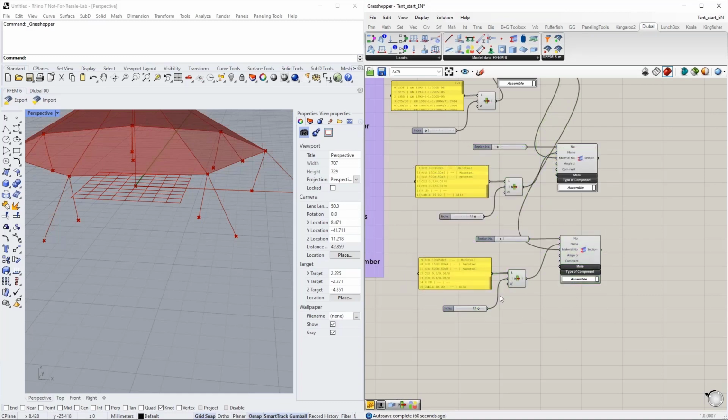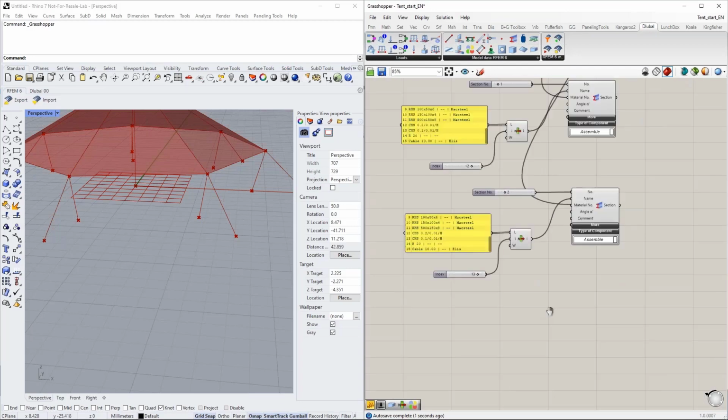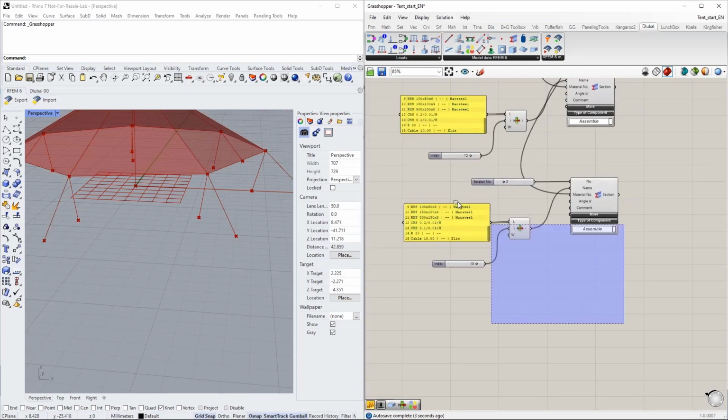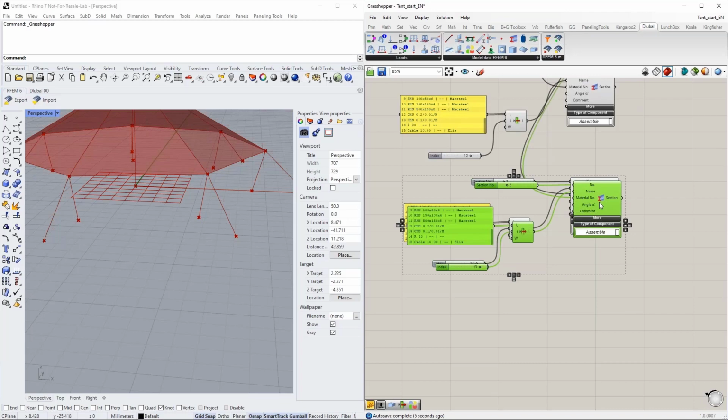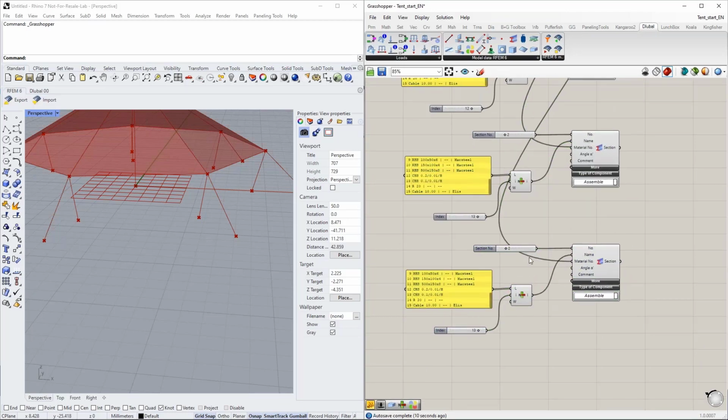because we have 4 different ones in here. The second one is cross section number 13 from that list. It's also a hollow cross section, but with different dimensions. I'm increasing the index number, of course. This is important. We cannot import different sections with the same index number.